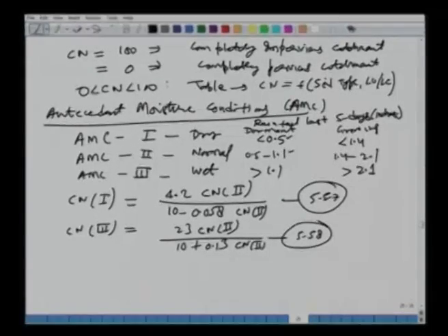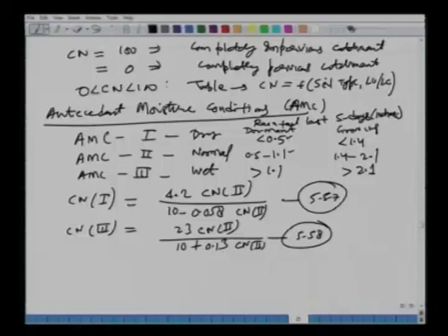You just find out what is the curve number in your catchment. Okay. Using the curve number depending upon AMC 1 or 2 or 3, depending upon the soil type and the land use, land cover conditions. Once you have done that, you can convert that Cn into S, all right, and then you can use that S in your basic equation for the SCS method. So, you can get the effective rainfall.